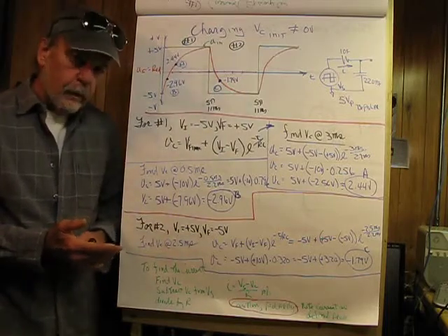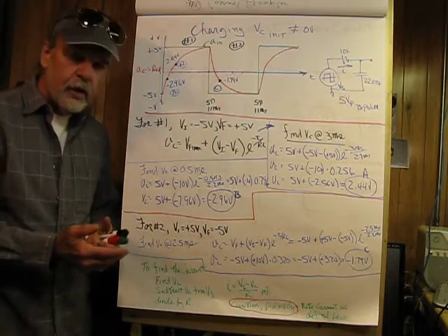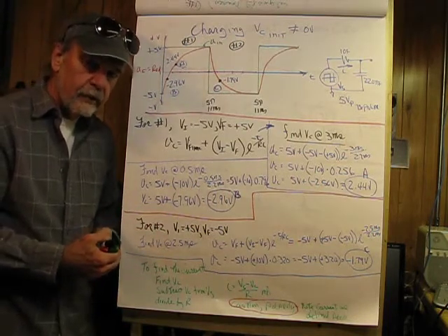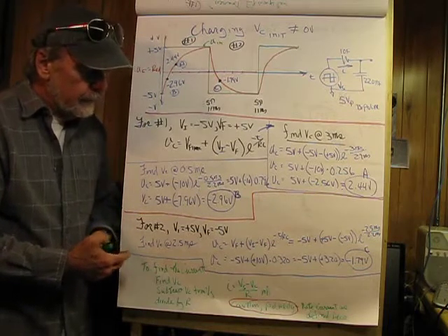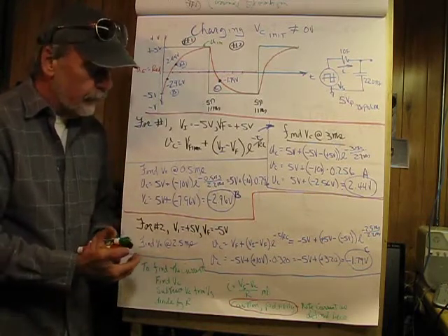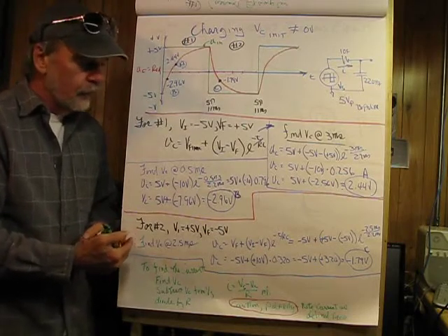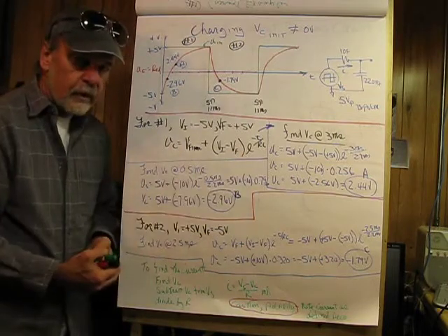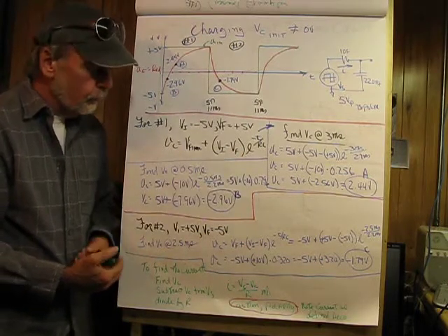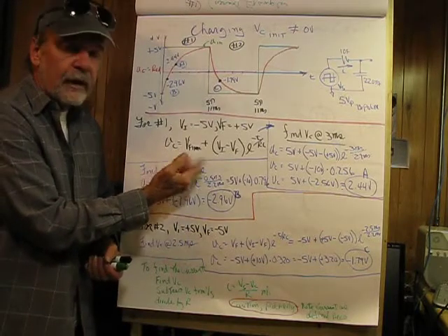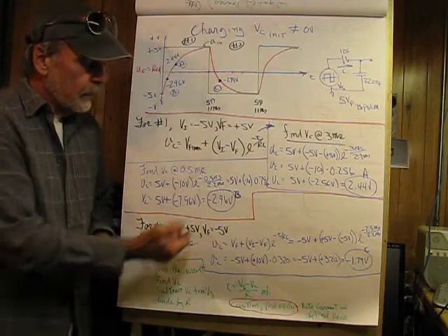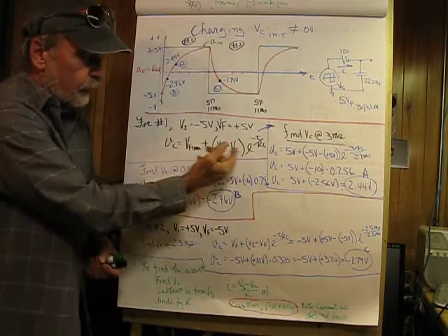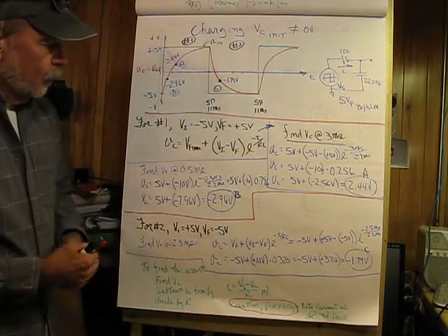Now, in the first part, we were looking at two different equations. One was a charging equation, which had the quantity 1 minus e raised to the -t over RC, and then we had the discharging equation, which was basically Vs times e raised to the -t over RC. We could use this equation instead of those other two if we so chose. All that would change is our final voltage, that's where we're going to, and our initial voltage is where we're coming from. So this is a very general equation, and we're going to start out here.